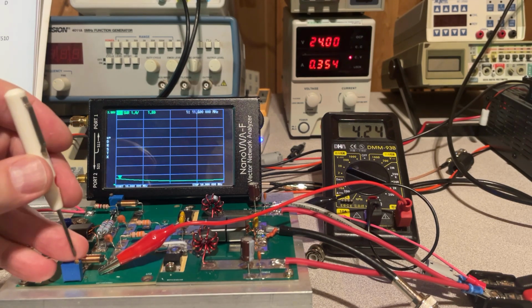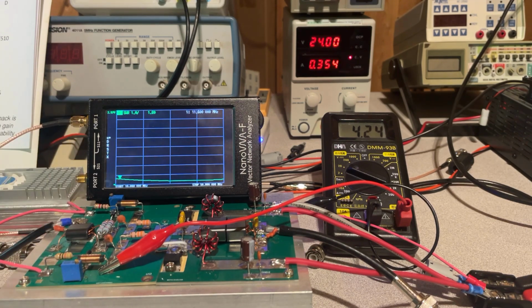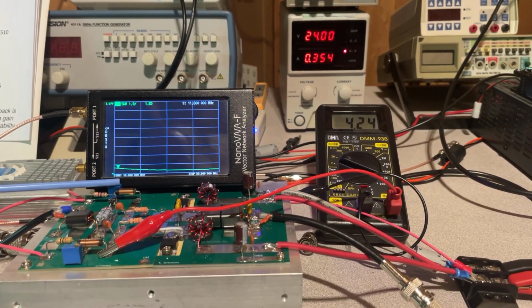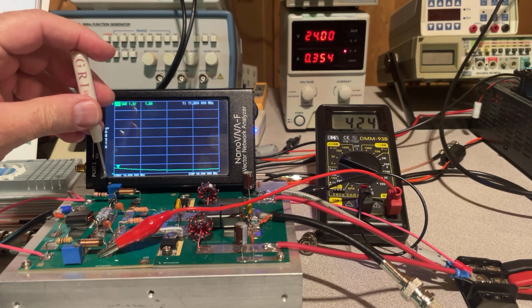Okay, now if I want to adjust that, I've got these two potentiometers here. Okay, this is for Q1, this is for Q2. These are multi-turn pots. Best to use multi-turn potentiometers for measuring and adjusting the bias voltage, so you have a little bit more control over the voltage level and a little bit more accuracy. So that's what I recommend.